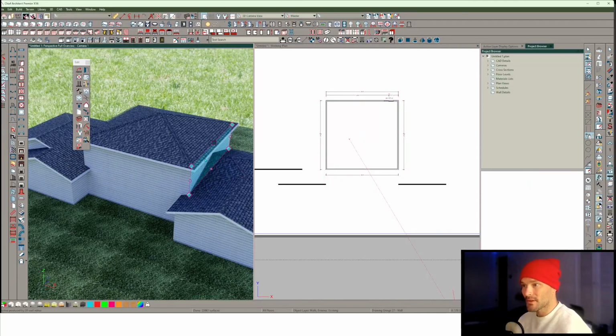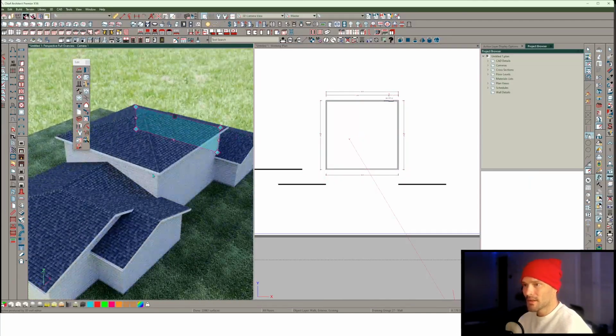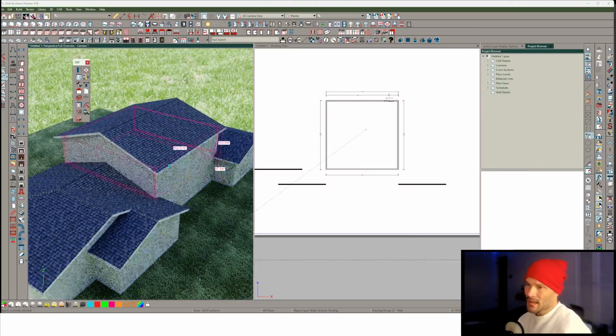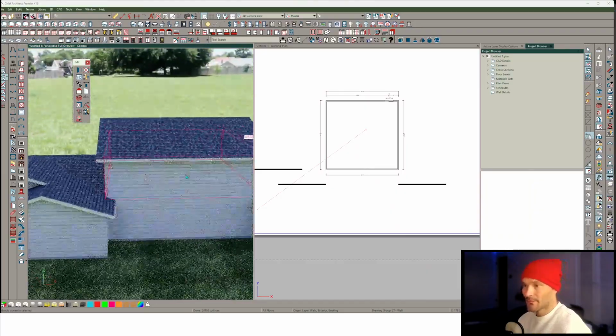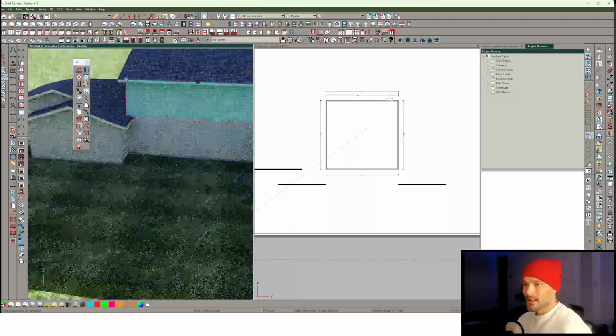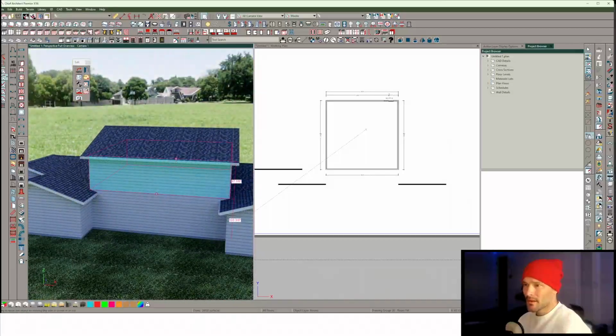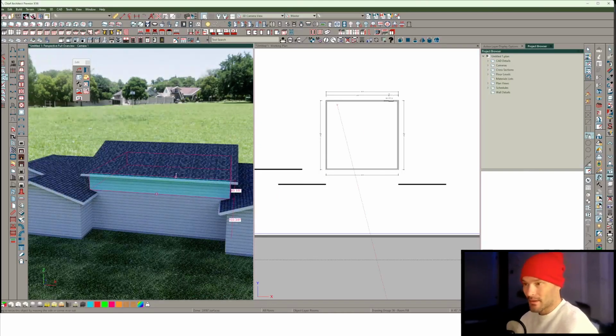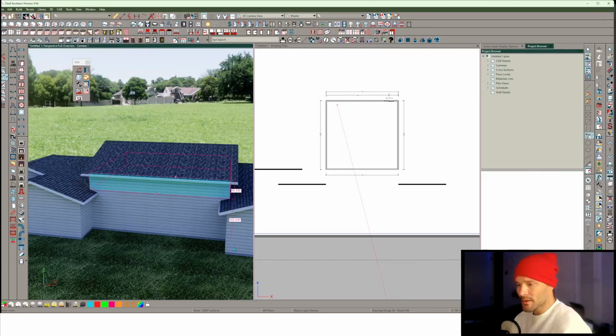to that structure that I'm looking for, where I can switch to our 3D view and control select two items, make them gable end walls, and I might even adjust the overall floor for this, which I could do by selecting the exterior wall, tab or enter, and then drag down the edit handle, which represents the floor default, and drag this down to what I need it to be. I'm just going to say 48 inches by using tab enter input method. And then on top of this, we do have an additional structure here, which is kind of the front patio, front porch, if you will.